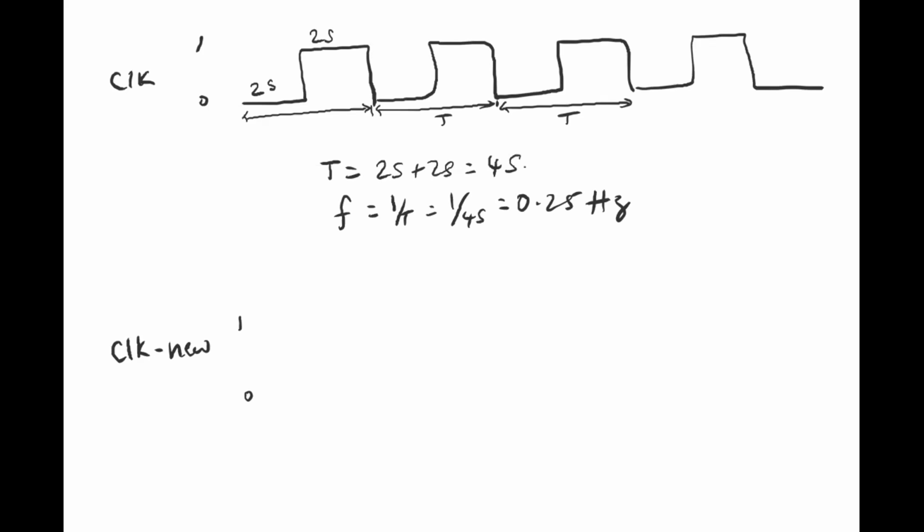You just need something to extend the period, like a counter or something. That is true, but before we get to the counter part, what I want to say is, by mentioning that I am dividing the clock, I am essentially dividing the frequency of the clock, or finding some way to reduce the frequency of the clock, right? Because my frequency is 1 by t, it is clear that my frequency is inversely proportional to my time period. So whenever I say I'm reducing the frequency, that means I'm increasing the time period.